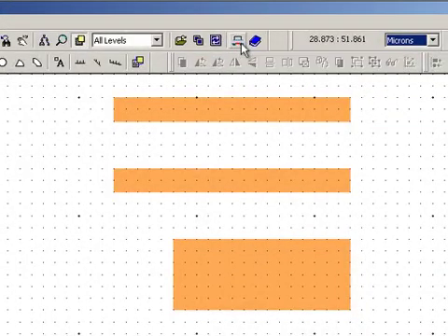Beside that, we have the ability to generate a cross-section view of the cell. And again, I noted earlier that LEdit can perform some advanced features, one of those being process modeling. This will basically build a 3D cross-section of your design based on your processing parameters. We really don't get into that function, so we're going to leave that one for advanced users. If they want to explore that later on, you can feel free to do that.